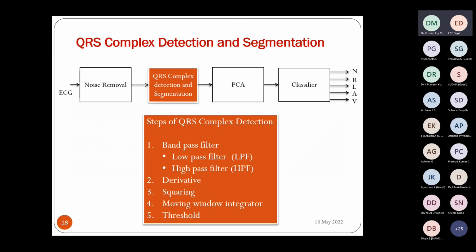So DWT reconstruction gives somewhat better performance compared to Fourier filters, because with Fourier filters, if the noise is present in the bands which are part of the signal, then when you remove them, part of the signal will also be lost. The signal will be distorted. The Fourier transform is not that efficient in denoising ECG. That's the reason we have gone to DWT based denoising.